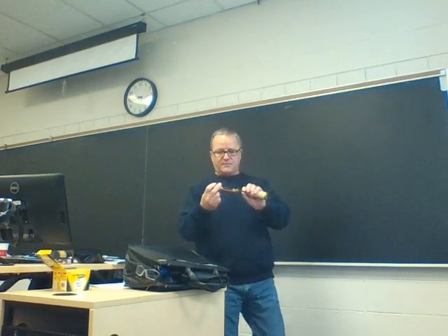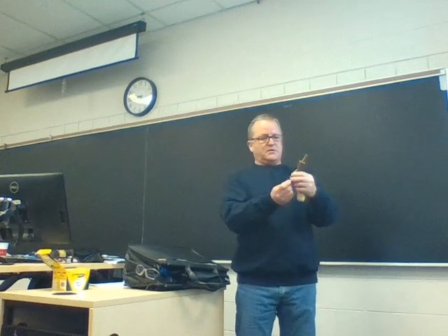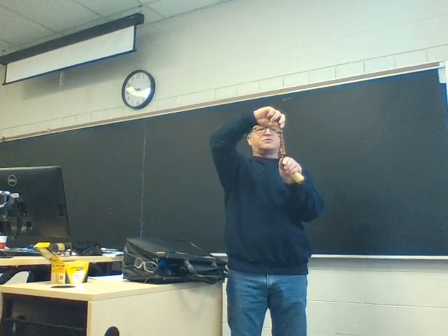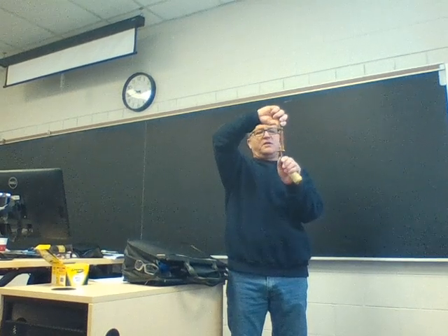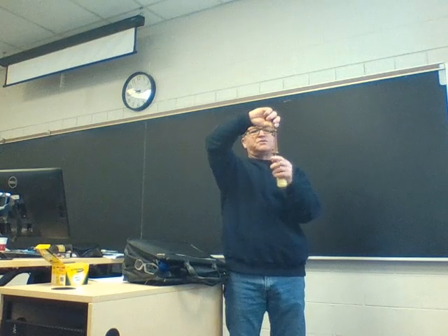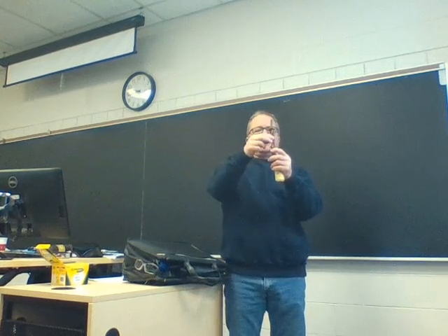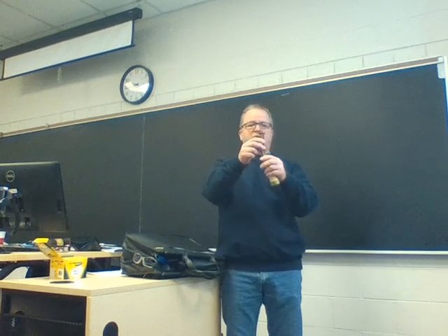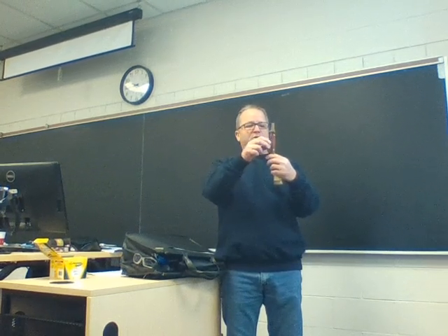On the fuse link here, one connection point of the fuse is on the top end, the bottom end is the other part of the fuse. Inside is this fusible link that will melt if there is too much heat, or if it's designed for a short circuit, it will open also.